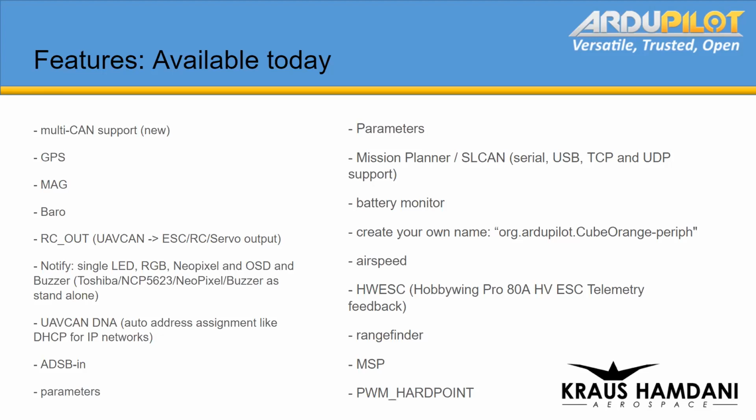That sounds a little funny, but I've been using some serial to IP converters, and then I can actually do an SLCAN on a serial port, feeding into Mission Planner, and so over UDP traffic, I can do firmware updates on my peripherals, which is just amazing, and configure them and all that.